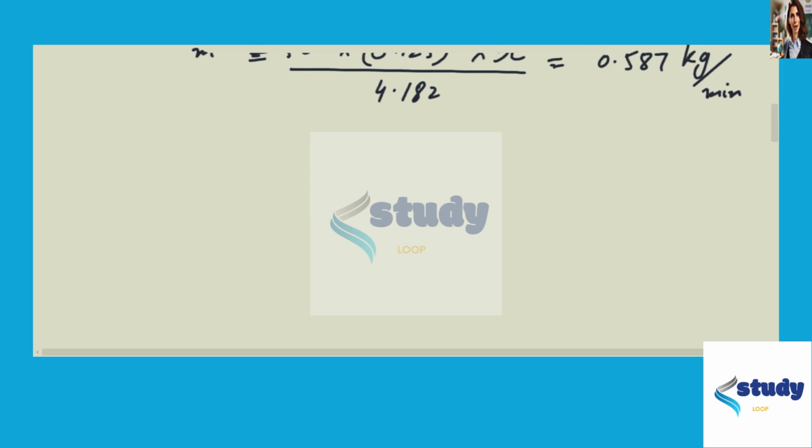Next we need to repeat the calculation for the exit point. For the calculation we will need the relative humidity, phi 2, equal to 100%, and the temperature, T2, equal to 100 degrees Fahrenheit. First we need the vapor pressure PV2, and from it the absolute humidity.